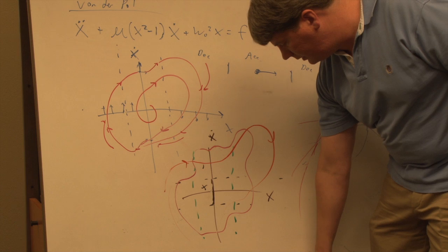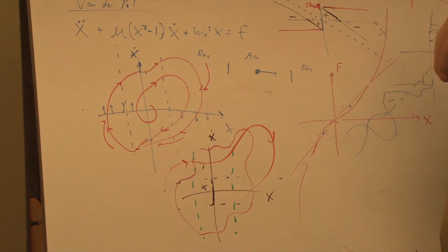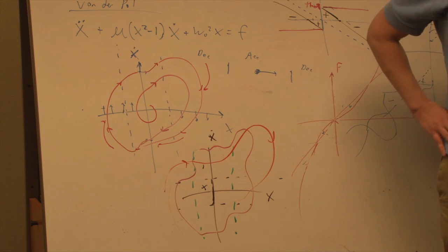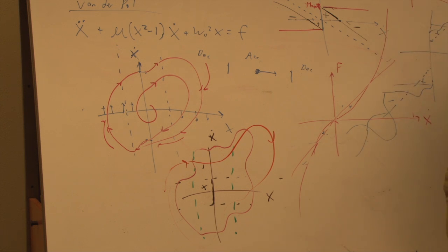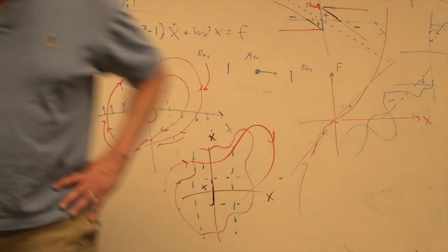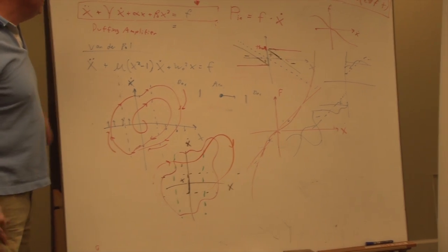So what Chris and I developed for an arbitrary thing is, I think, a classic oscillator. I'd have to check the literature, it might not have been developed yet, but where the Van der Pol changes the damping based on x to either drive or diminish for a steady state amplitude. We used a bistable spring in addition to a restoring, greater nonlinear spring. And so by shaping that contour, we got the behavior that we wanted, and we can even modulate that. But I don't know if that's a new class of oscillator in the mathematical literature, in which case we should claim it, or if someone's done it, and we should look at that.